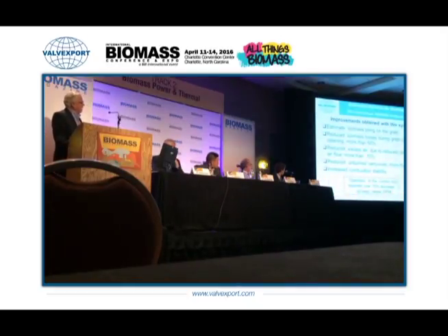You can obtain a 50% reduction in the biomass lost through carryovers. You can obtain 10% or greater reduction in excess air, because the typical operator increases excess air as soon as he sees that he has some problems with distribution of the biomass. And the unburned carryover, and definitely increased combustion stability. Operators in control room reported over 15% decrease in biomass feeder RPM.